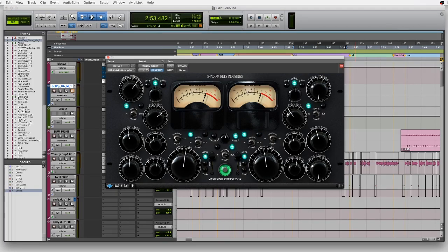When the sidechain filter is engaged, any input signal below 90 Hz will not affect the amount of compression applied going through either stage. This is helpful when low-end material such as a kick drum is causing unwanted pumping effects to the signal. The output transformers provide control over the tone and vibe of the audio.